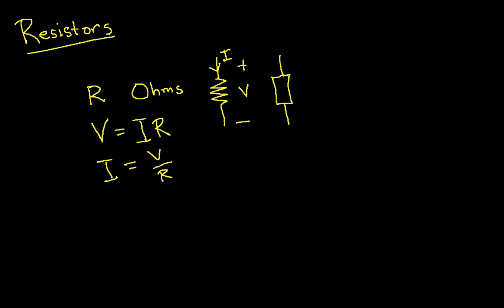So if I were to give you voltage and resistance, you could compute current. And sometimes, we don't do this that often, but sometimes our goal is to determine what a resistance is. And so if we can measure voltage and current, we can say that the resistance is the voltage over the current. So those are all examples of Ohm's law.